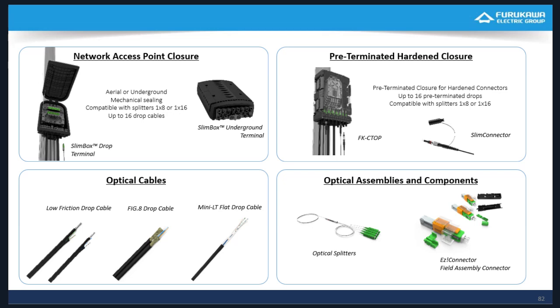Why are they like that? Because when you have to connect a customer, the environment is pretty aggressive. You have a lot of corners, you don't have too much space. People don't want to see the cable in their home, so you have pass-through duct. So the fiber bend sensitivity is really a matter here, and it's really important. And we also have the accessories like connectors, splitters, for that part of the network as well.